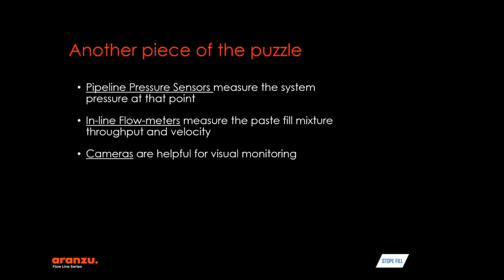Inline flow meters measure the paste fill mixture throughput in the pipe and are extremely helpful in identifying early onset of a blockage condition. If flow is reducing with the pressure increasing, then a blockage condition is developing. It also helps in showing the blockage response is being effective.